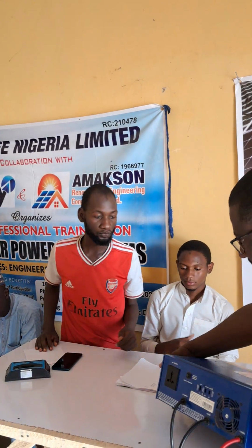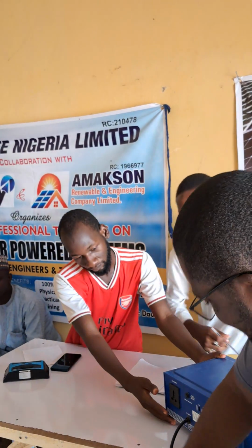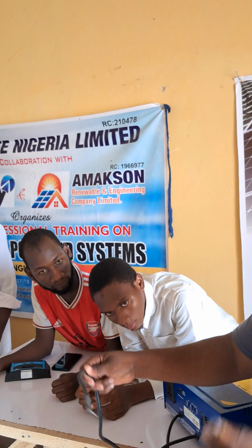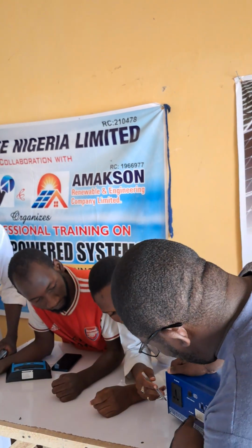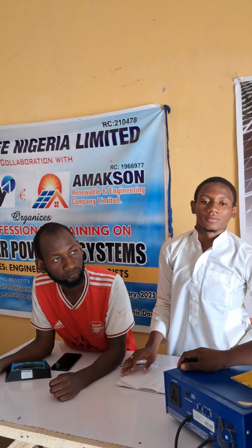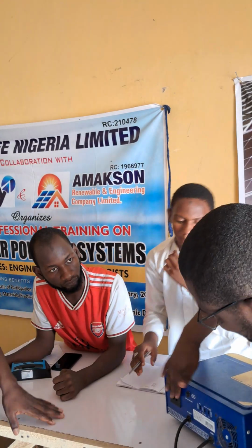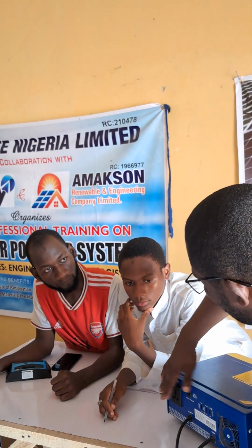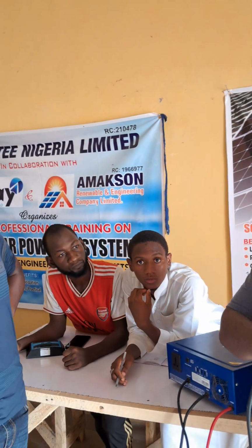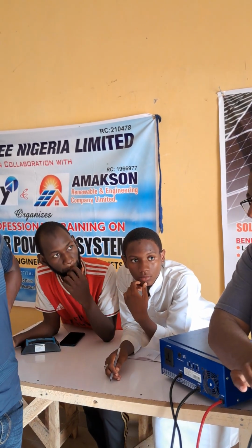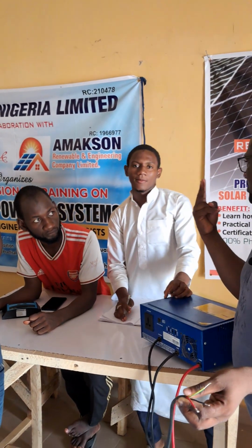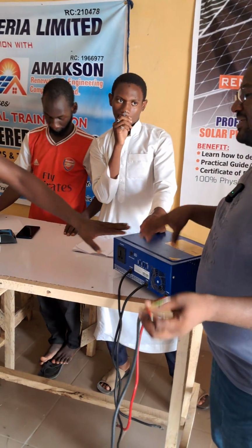Look at it here. This is our polarities from the inverter to the battery, plus and minus, right? Can you see, what did you see here? AC input. You connect this to the socket outlet. Do you understand? And this is AC output. This is what the inverter will give to the home appliances. While this one, you are connecting it to the plug of the national grid to pass through the inverter, so that in case you want to charge your batteries through the inverter, you can have dual source of charging, solar panel and the inverter itself.